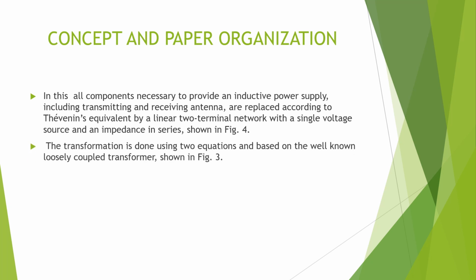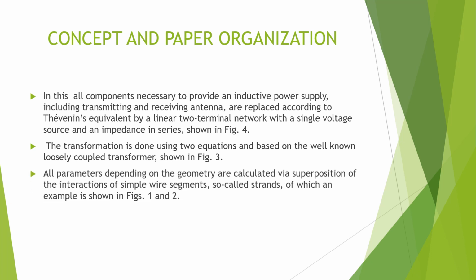The transformation is done using equations and is based on the well-known loosely coupled transformer shown in figure 3. This figure 3 is also in the next slide. Now let's move to the next point. All the parameters depending on geometry are calculated via superposition of the interactions of simple wire segments, so-called strands. As an example, figures 1, 2, 3 and 4 will be shown in the next slide.